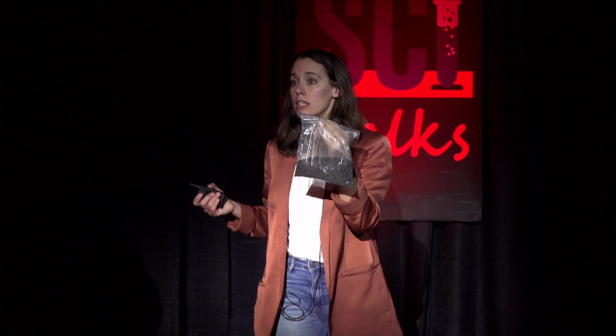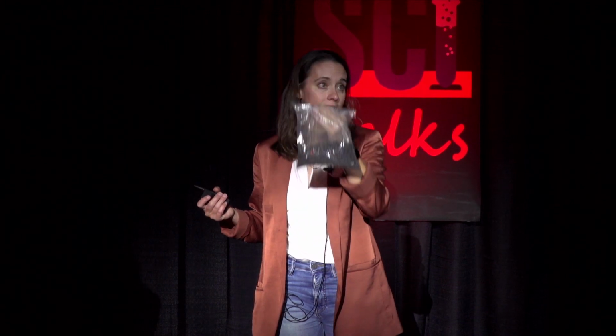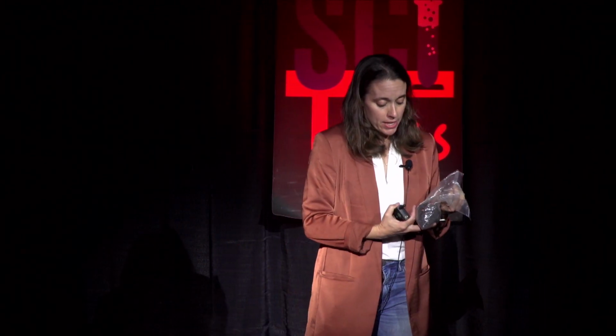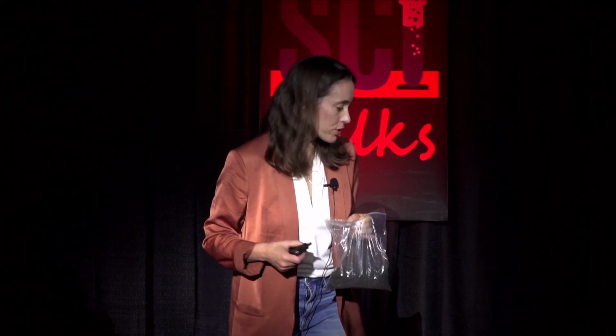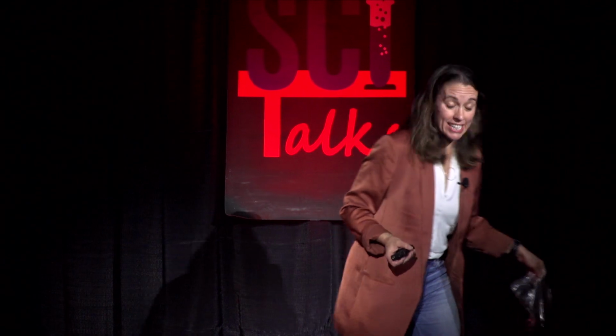We use this for the grit on our roads in the winter. When the roads get slippery, you can buy this at Landscape Connection. This material naturally comes to us pretty porous because of the way it was formed from those gaseous volcanic eruptions tens of thousands of years ago. So we look for surface area. You can get it by grinding and crushing.